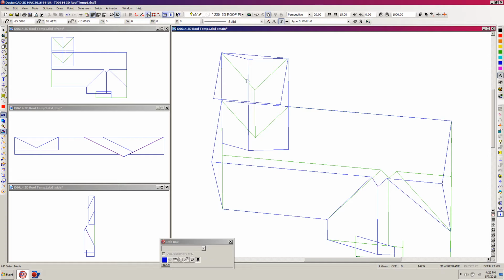So now I need to deal with this guy here, and in order to do that, I'm just going to use the surface intersect command. I only need to do it once this time, and I'll show you why. Clicking on surface intersection, click on this guy here, and then this plane. And there it is. So now I can click on that plane, right click here, and bring it over to this point at the ridge. And this one I can hit Control Shift and watch my cursor turn to a minus. And I just left click and it deletes that point. So now I have the end of my hip, but I still have to adjust these guys to it. So I can click on this one and just right click, and it brings it down. Now I can click on this one and right click, and right click.